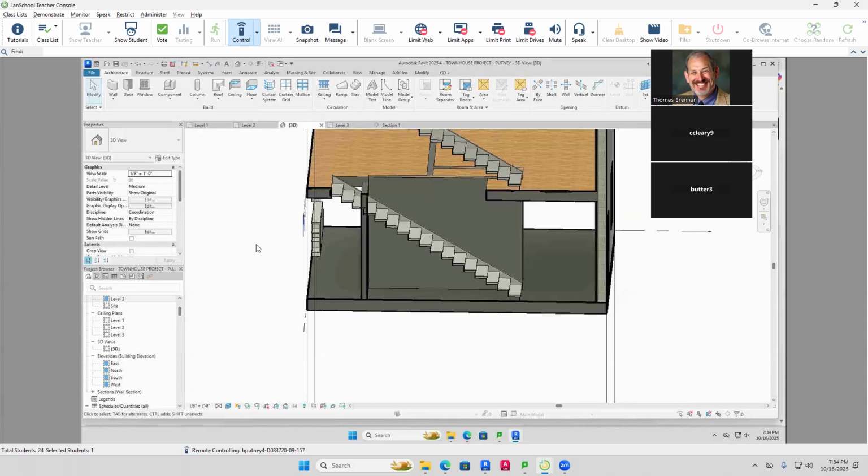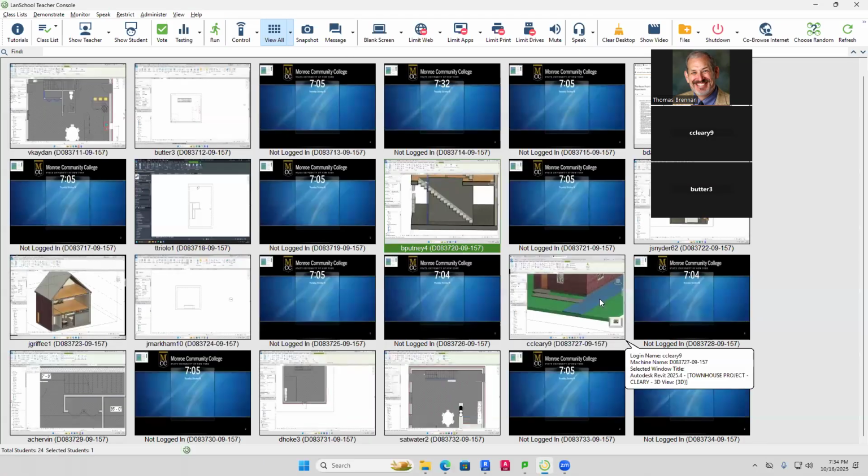Create a floor plan. Create stairs. Yeah, create floors. The exterior walls are level 1, tops unconnected 20 feet. But if you're going to connect them, you have to make them a little bit shorter. So you could get by with 1 foot, I think. Take a look at some other views and see if that doesn't work. I think you should be fine now, though. All right. Thank you. Sure.